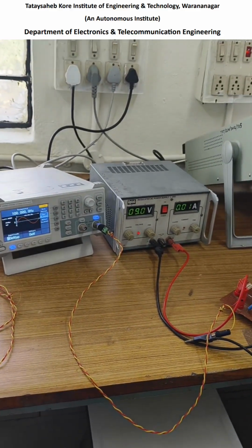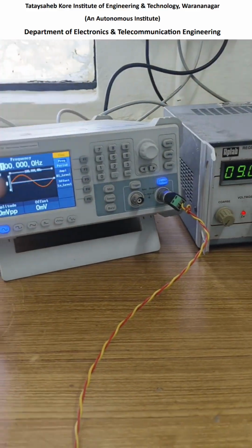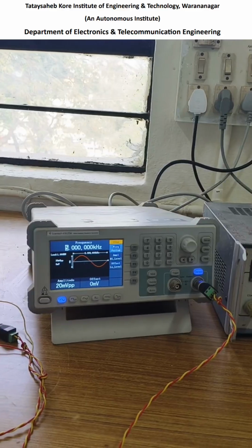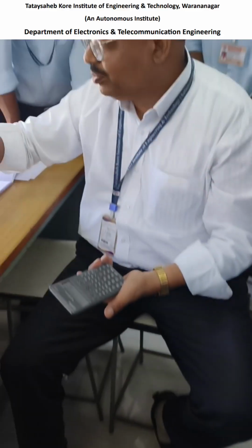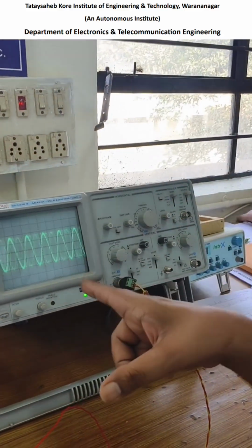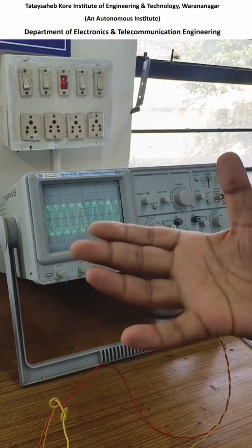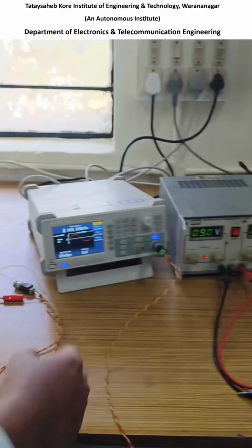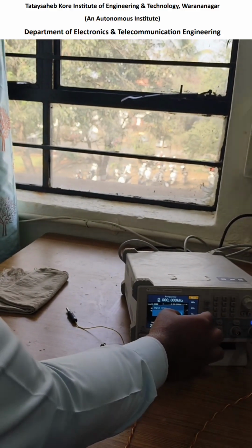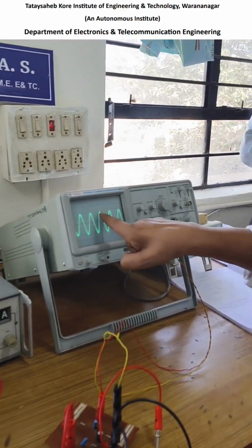Now you make it 5 kilohertz. Now first take the blinker on frequency. So press F1 first. Correct. Now make it 5 kilohertz. Press 5 and kilohertz. That is 5 kilohertz. Right? Now carefully see here. If I adjust this, now here I am getting the same value. If you increase the value, now make it 50 kilohertz. Press 50 and then kilohertz. 50 kilohertz. F2. See here. Again, the gain remains constant.